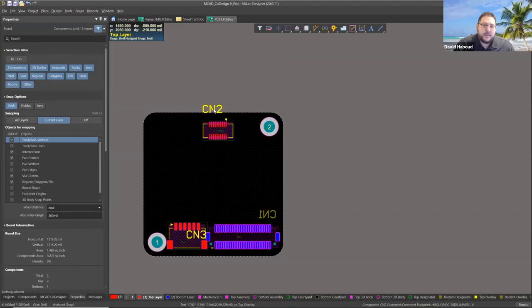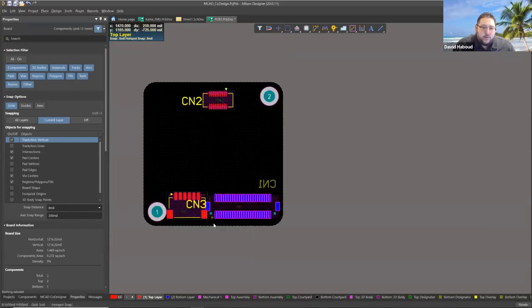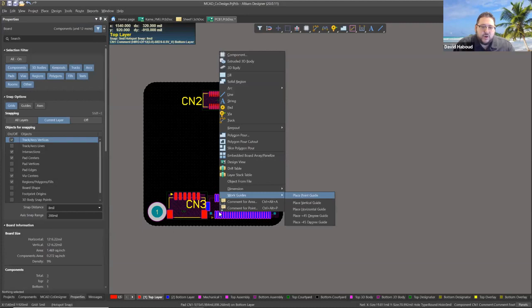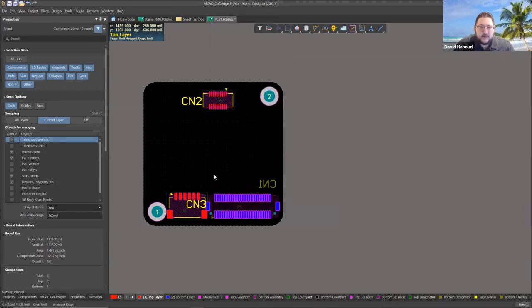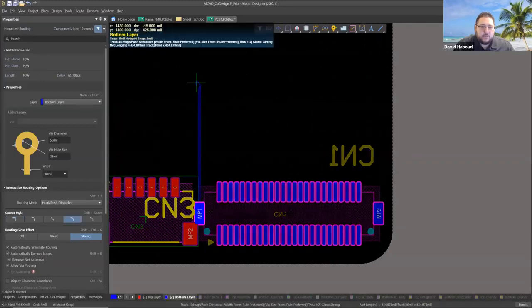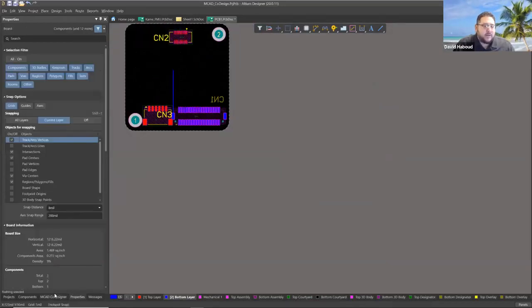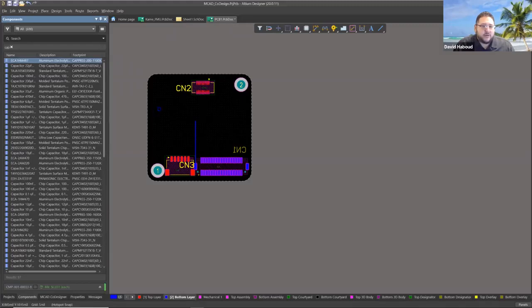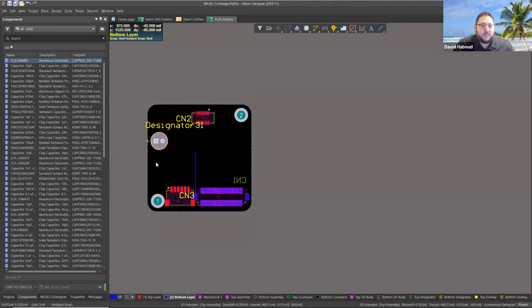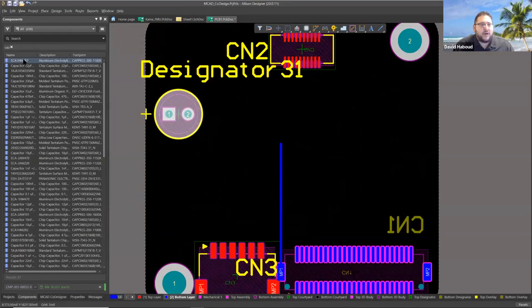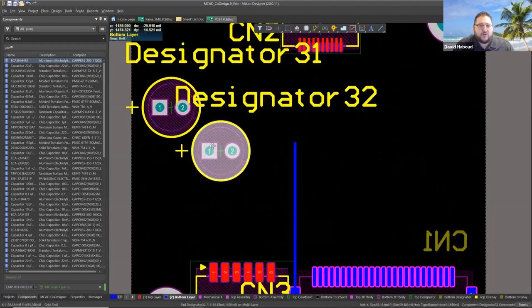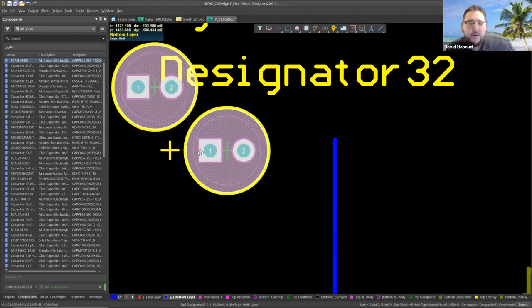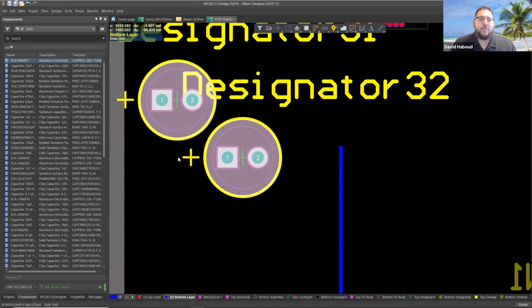So we have this done here. This is obviously off the board, so I'm just going to throw it back on. What else? Let's see. In order to show you the capabilities of the copper placement, why don't we add a little track right here? And of course, it's not just placement on the mechanical side, there's also placement on the electrical side. So you wouldn't obviously place something this large, but I just want to show you a functionality that was introduced in Altium Designer 20. So when you define a component courtyard layer,